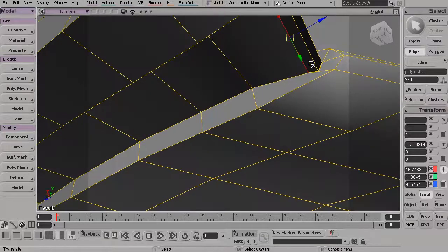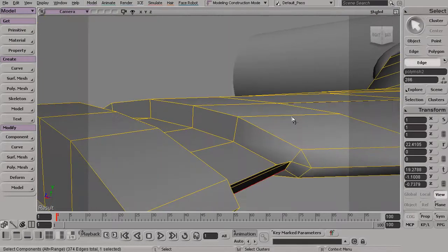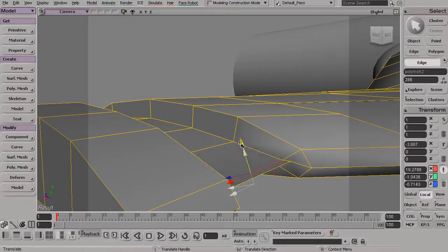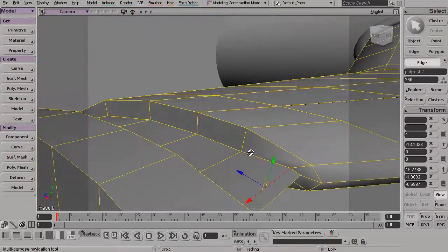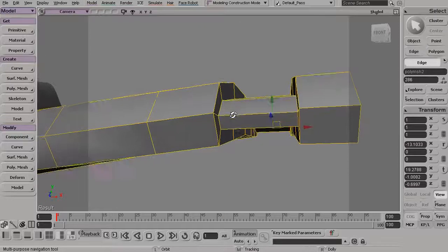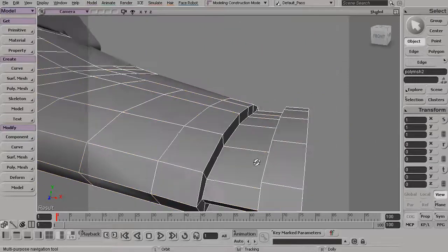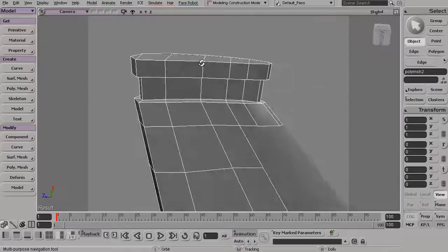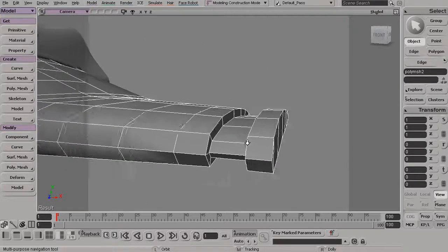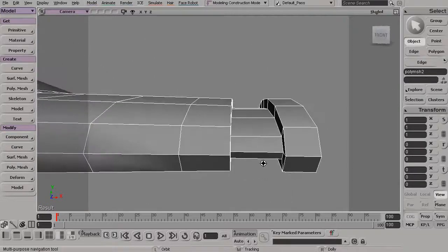Okay, we'll swing right underneath here. And again, press the I key to try to grab that edge. Back to V, and pull that out. Again, just trying to fix up some of that folding and interpenetration that we had back there. Okay, and now you can see we have performed our first extrusion. So pulling that in and making a nice little lip there.